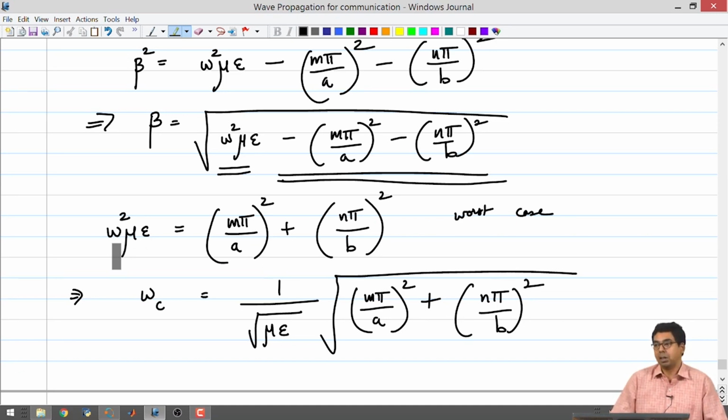We will then talk about what are known as phase velocities and group velocities. We will also talk about dispersion. It is a very important thing, because if the waveguide has two plates and you have vacuum or air filling it, we already know from our prior classes that vacuum or air is a non-dispersive medium. But if you make a waveguide out of it, suddenly it becomes dispersive. That is, it will have different values of velocities for different frequencies. So, omega divided by beta, d omega divided by d beta, all these things we will be seeing in the next class. Okay. So, I will stop here, and we will meet in the next class.